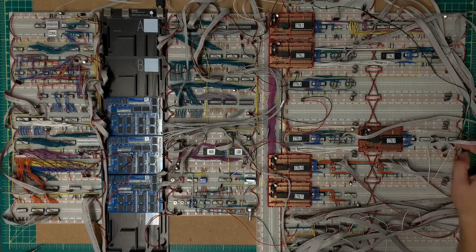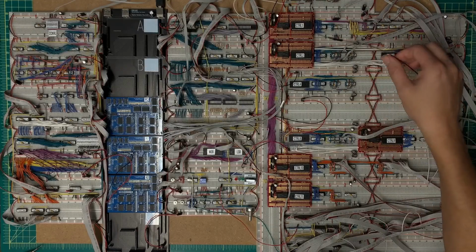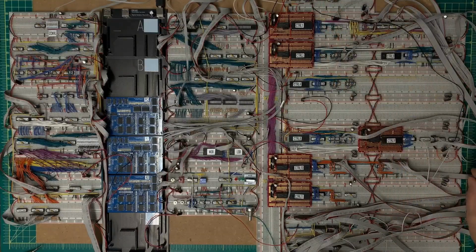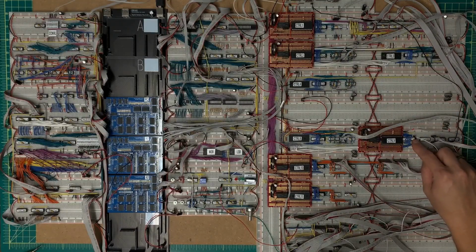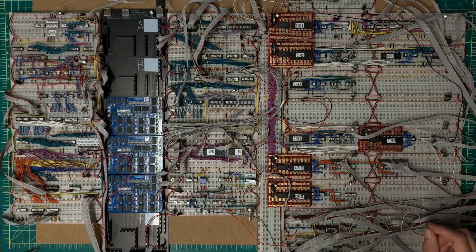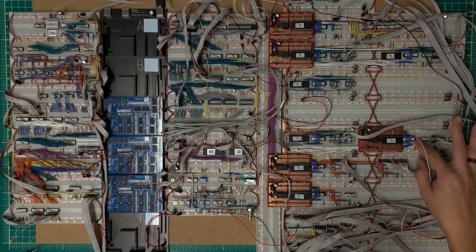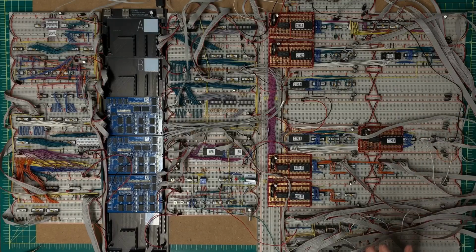Now, the least significant bit is my new signal here, and it is ANDed with a delayed clock all the way up here in my clock delay, calculating my spike clock circuit, but that's okay. There are 5 signals here left to be wired up. These are the interrupt context latches, similar to the 5 signals over here. And while I'm messing around in here, I think I'm going to go ahead and get those wired up, even though I have nothing that will use them yet.